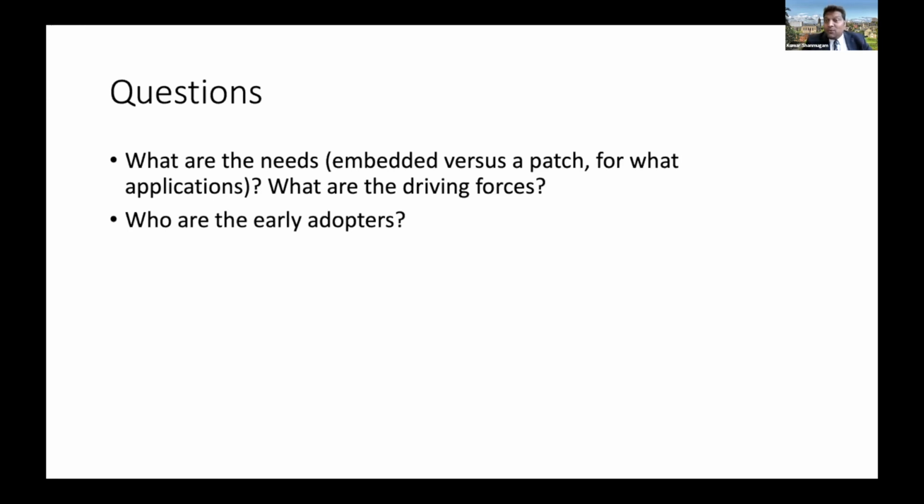I'm sorry about that. So we explored polyethylene and polypropylene, particularly incorporating carbon nanotubes to enable self-sensing. And just to address your question, there are some portable printers which can be used to put some kind of smart patch on these pipes to monitor their structural health. I don't know whether it's practiced even in the aerospace industry, but to repair corrosion-related cracks or surface cracks on the aircraft fuselage, they use portable 3D printers to patch these cracks.